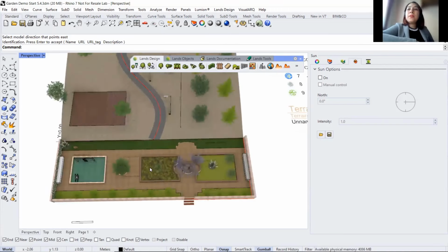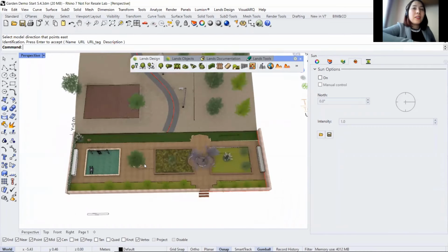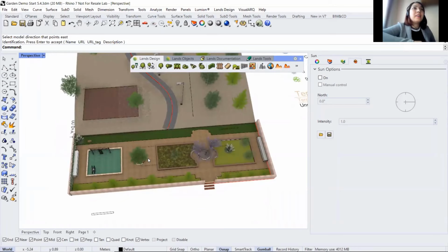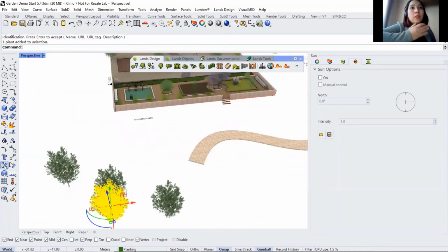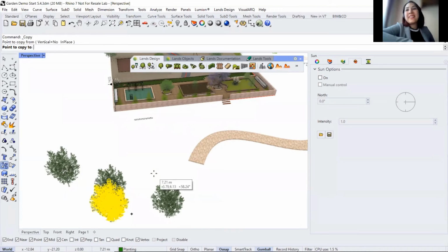Well, actually, there is no specific tool for that, but you can use the irrigation tools for indicating your drainage system instead of irrigation, or you can draw two different layers, two different irrigations, and call one of them drainage. So yeah, there's a workaround.